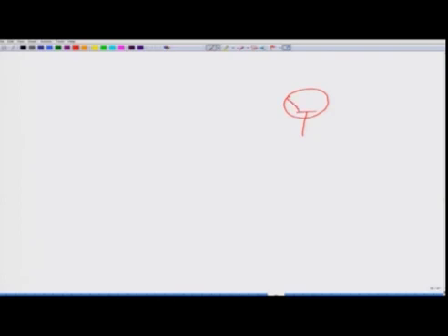Generally we keep it on left. So, this is the input, this is the emitter side and this is the collector side, and let me do it for NPN. So, the arrow should go from P to N, and hence the arrow should go this way, NPN. So, this base is now P and this emitter is N, collector is also N. So, emitter will have this arrow going from P side to N side, and then our circuit.